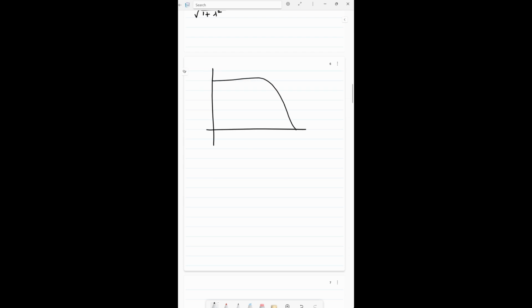Meanwhile, we'll just draw the frequency response of the Butterworth filter. As you can find, it is monotonic. It's a monotonically decreasing function. As omega increases, you can see that the gain is dropping. The passband frequency is omega p and the stopband frequency is omega s. The maximum gain will be 1 at 0 frequency. And according to the question, the gain is 0.9 at omega p, and at omega s, the gain is 0.2.